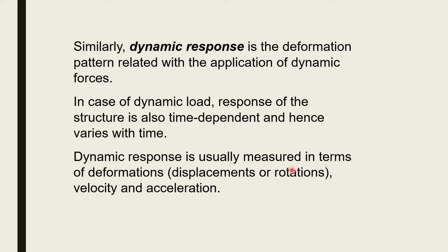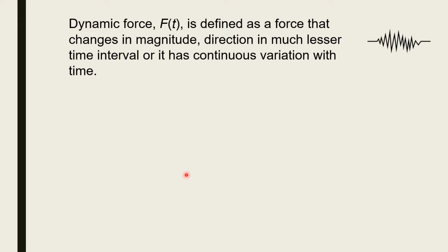Dynamic response is usually measured in terms of deformations, and deformations are displacement, rotations, velocity, and accelerations. Dynamic force. Dynamic force is defined as a force that changes in magnitude and direction in a much lesser interval of time, or it has a continuous variation with time. Here you can see as the time is changing, their magnitude and values are changing. This is an example of dynamic force. There may be a regular pattern or irregular pattern, but definitely the magnitude and direction change in a very small time.